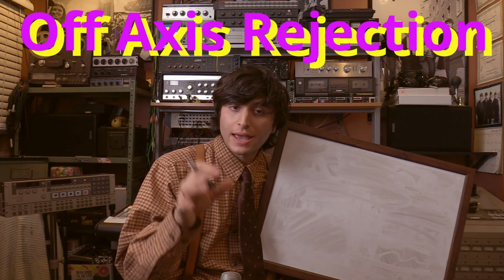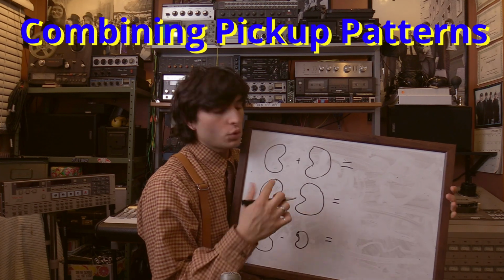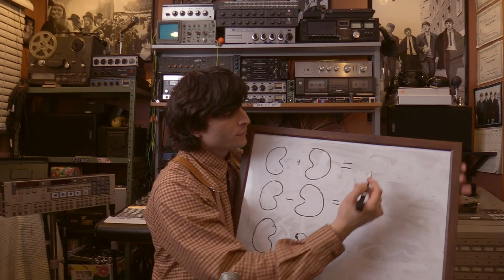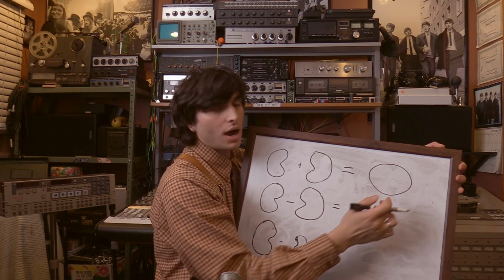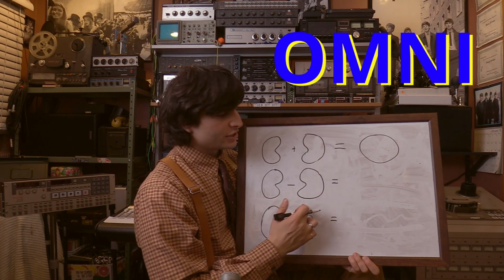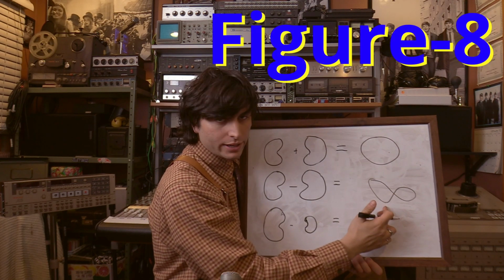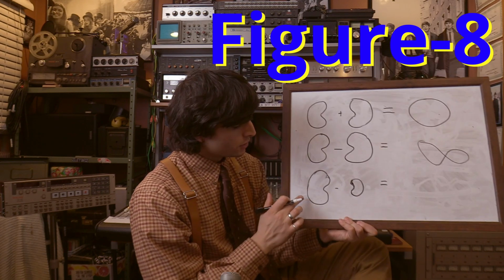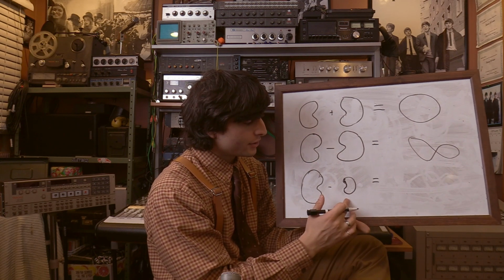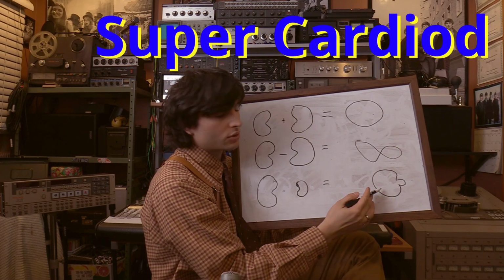Now, these pickup patterns can be combined with two different microphones to create different effects. For example, if you take two cardioid microphones, point them in opposite directions, and sum their signal, you are going to get an omnidirectional pickup pattern. If you do the same, but you subtract their signals from one another, you get a figure 8 pickup pattern. Now let's say you take that same cardioid pattern and you subtract the second cardioid pattern, but with an attenuated signal. You are going to get something like a supercardioid pattern.